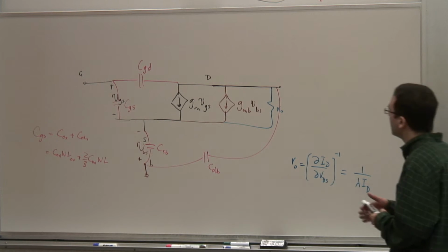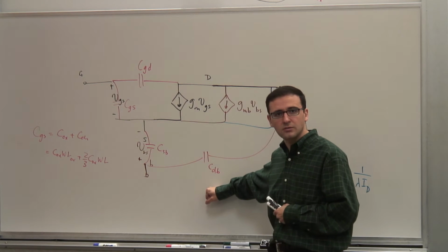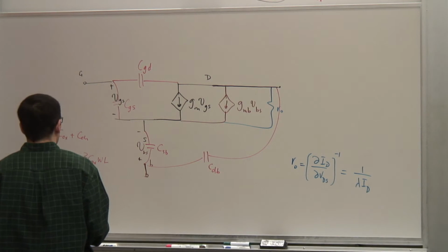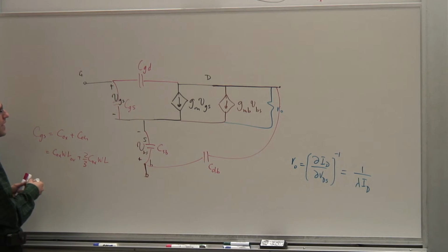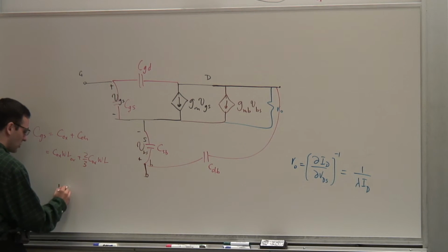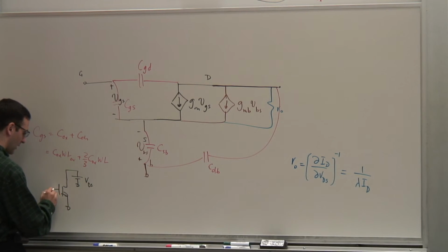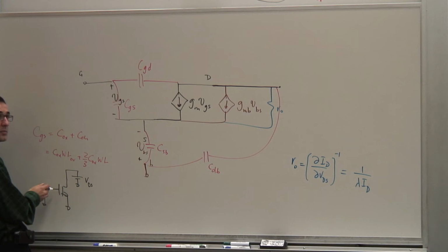Now, in a similar way to a bipolar transistor, I can actually calculate the cutoff frequency. The frequency at which the current gain becomes 1 for this transistor. Right? And when you do this calculation, basically, it's an arrangement in which you have the drain kept at some constant DC voltage, and you're applying a constant voltage here. Or you can think about it this way. You're applying an AC current. You don't need any DC current because this can't absorb any DC current.